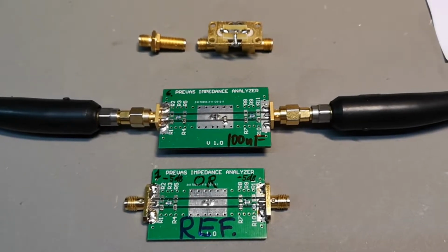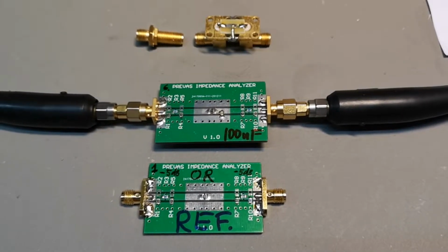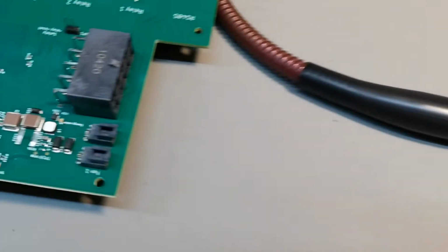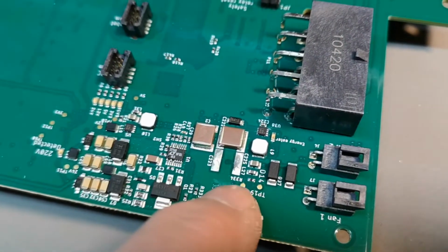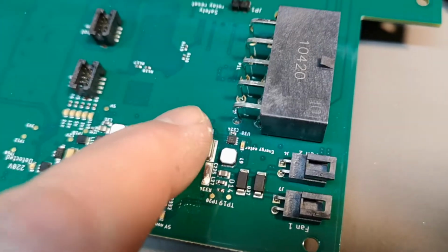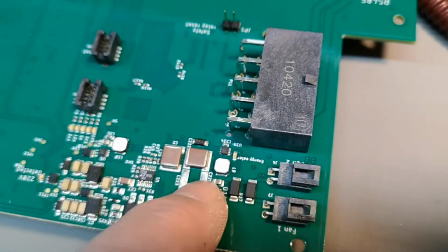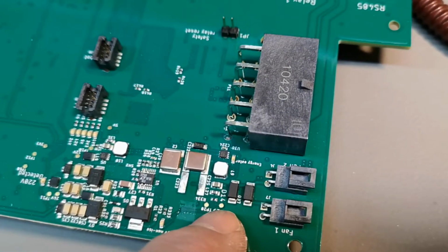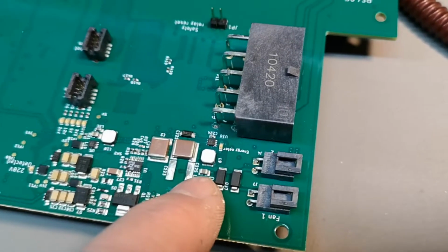This is why we have all sorts of EMC problems, because we use components differently, and so they perform a little bit different from what is expected. For example, here is a switch mode power supply with some really big capacitors, and this was of course supposed to perform really good, but when it was implemented with the way that stuff was connected together with long thin wires, everything became resonant, and we had a huge EMC problem from this switch mode power supply.